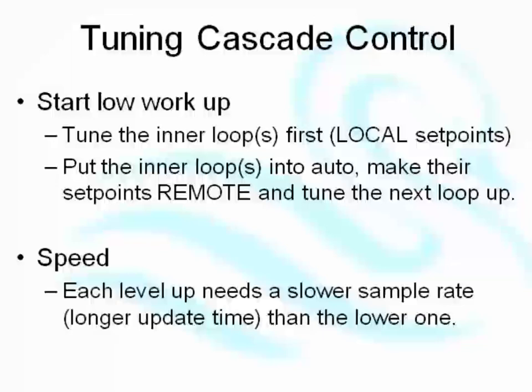You completely forget the fact that it's not actually controlling a valve, it's actually controlling the set point of something else. You forget that, you just tune it as per normal. You do the open loop bump, you calculate your time delay, your time constant, your open loop gain, put those values into the equations, get the P and I values, put those in, so it's all the same.